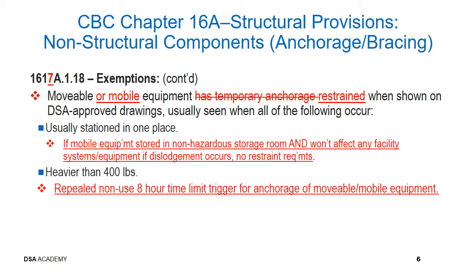Mobile equipment shall be restrained when not in use and is stored unless the equipment is stored in a storage room that does not house hazardous material or any facility system or fixed equipment that can be affected by mobile equipment lacking restraint. The non-use 8-hour time limit which triggered anchorage of movable mobile equipment has been repealed.